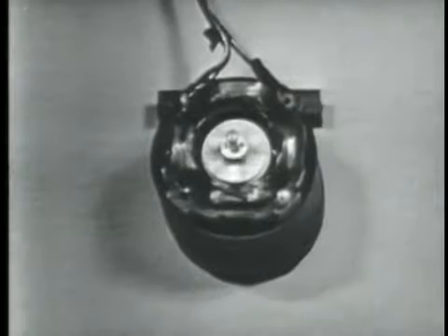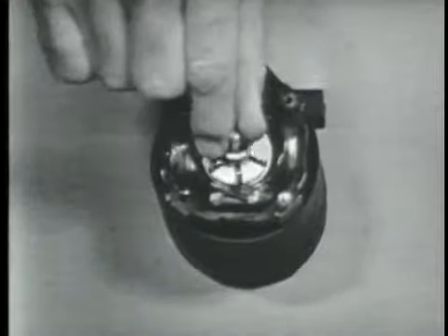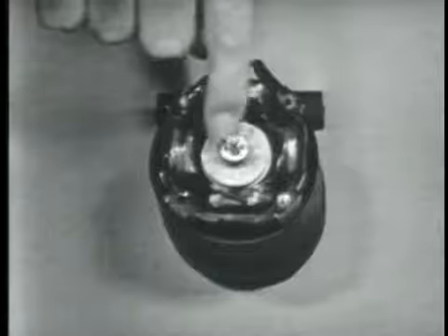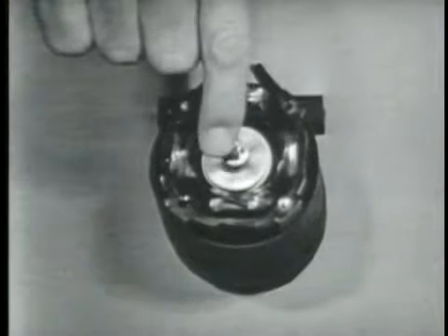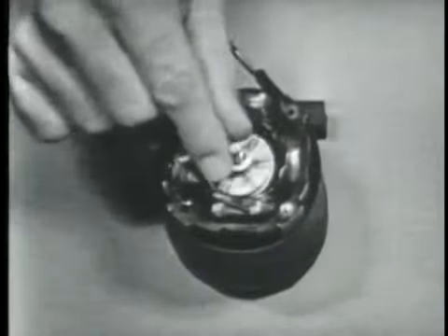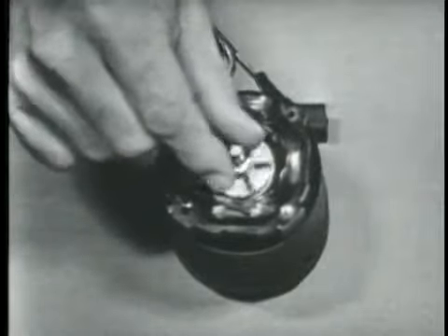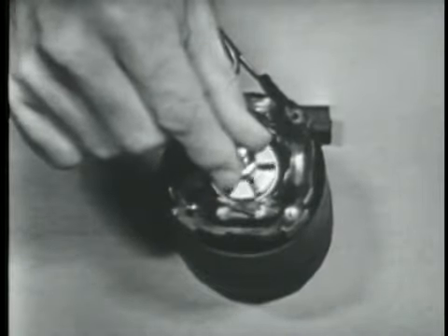Which brings us to item 5, which I believe you can have. Exactly. All right, the rotor of the induction motor does not rotate as fast as the magnetic field because of several forces that act on the rotor. One, the internal load, that is rotor weight, the little fan, the bearing friction, and so on. And the external load on the motor, such as the gears, pulleys, or the fan blade, or in this case, my finger. As I squeeze it a little bit, you can see that it turns slow. Right. Whatever work the motor must do.